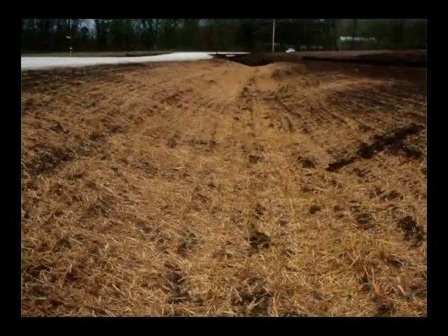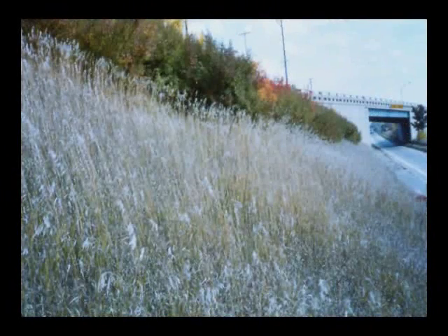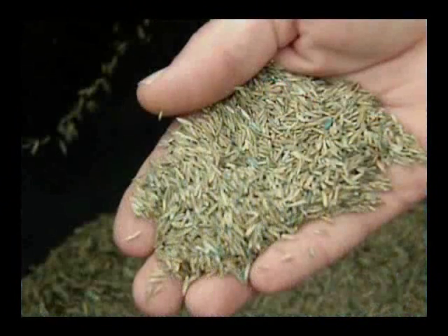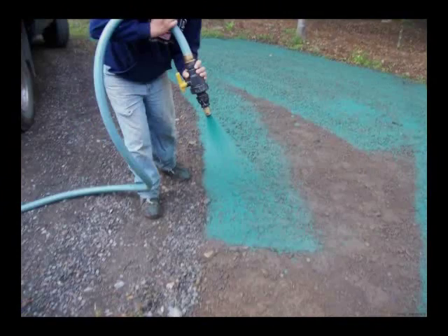Seed and mulch all areas that have no vegetative cover as soon as possible, but no later than 5 days after achieving final grade. If it is not feasible to permanently seed, establish a quick-growing temporary grass cover or install appropriate temporary SESC measures. Seed may be applied by hand, mechanical spreader, seed drill, or by hydroseeding.